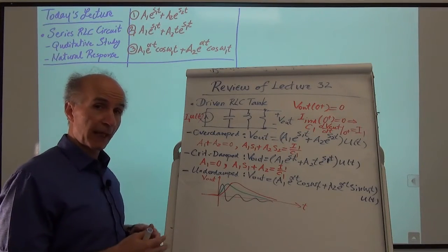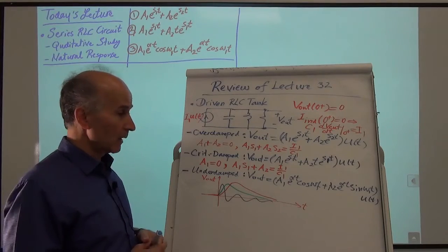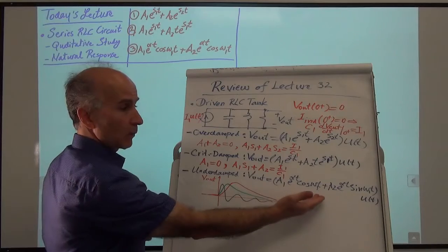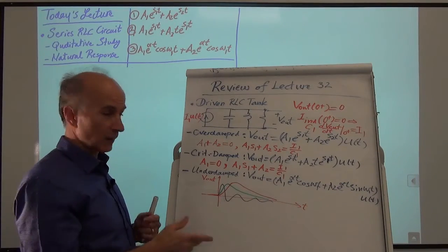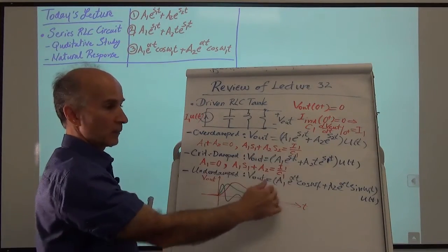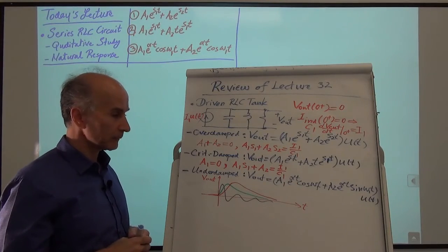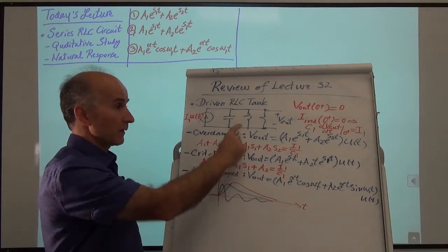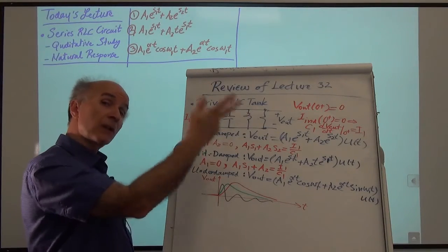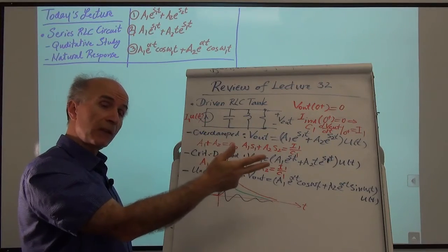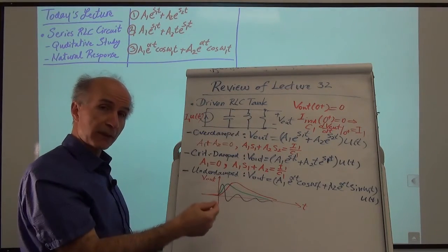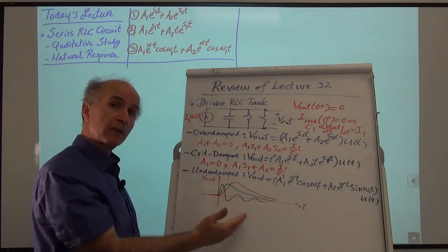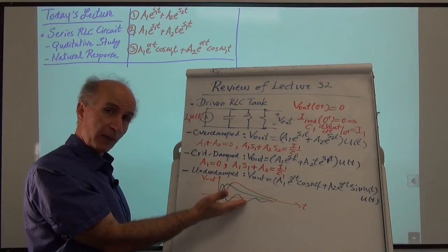And finally, if we have an underdamped response, meaning that this resistor is large enough, then we have this equation, the third type of response, and then we have to go and satisfy both of these, which I didn't bother with here. So generally what we saw was that the output voltage as a function of time starts from 0, as we saw, and eventually also goes to 0, because at time infinity, this inductor acts as a short circuit and brings back the voltage to 0. Now, how it goes from 0 to 0 depends on the type of response that we have.